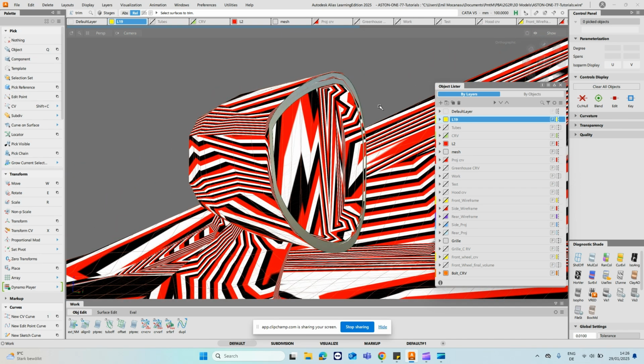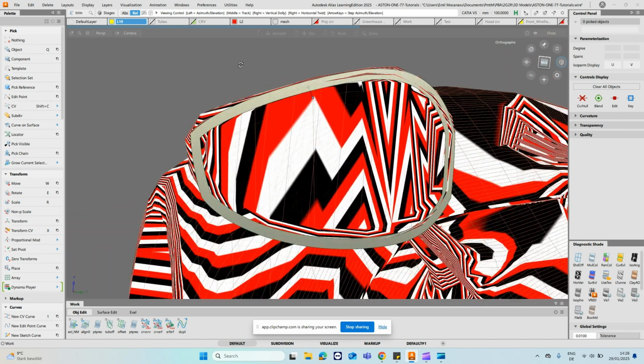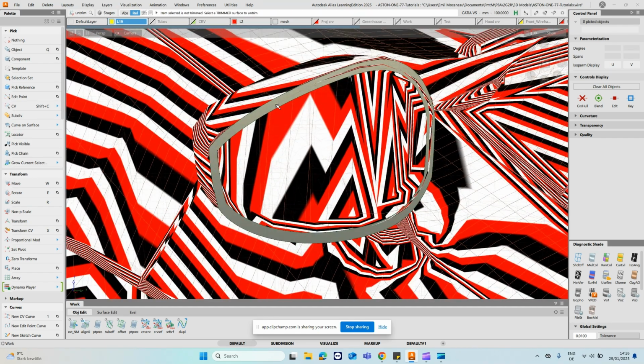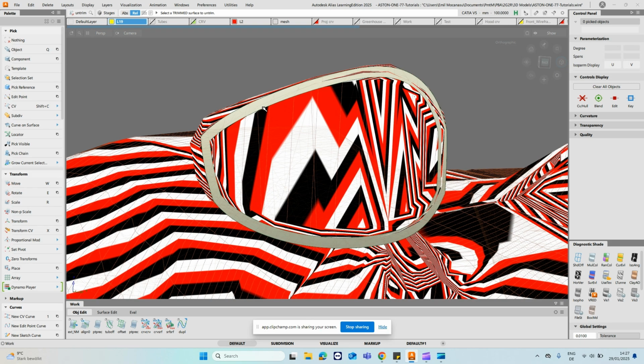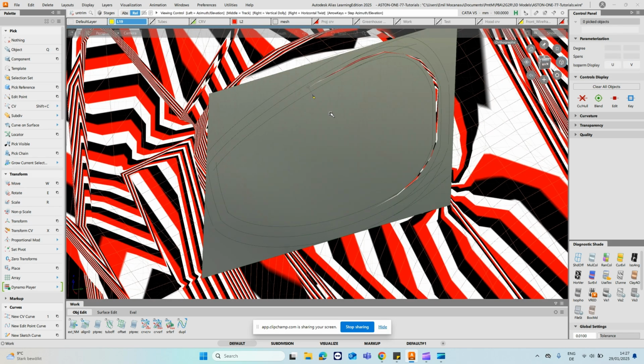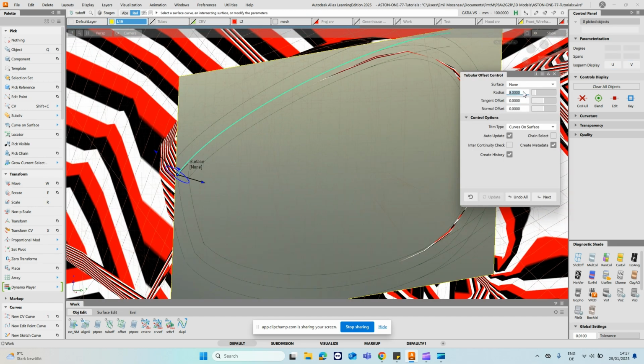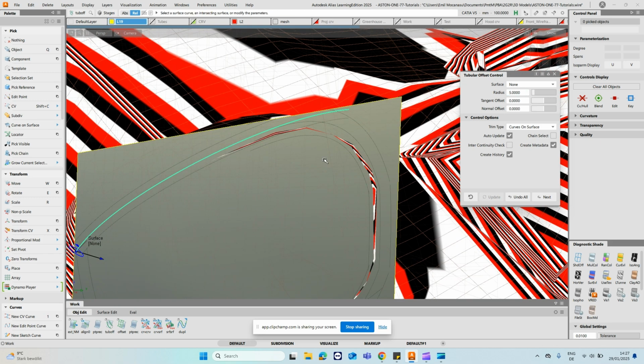I guess we could go somewhat thinner. So let's do that. So untrim this. And then we just query edit these, and instead of 8mm, let's say 5. And you can notice that these get smaller.